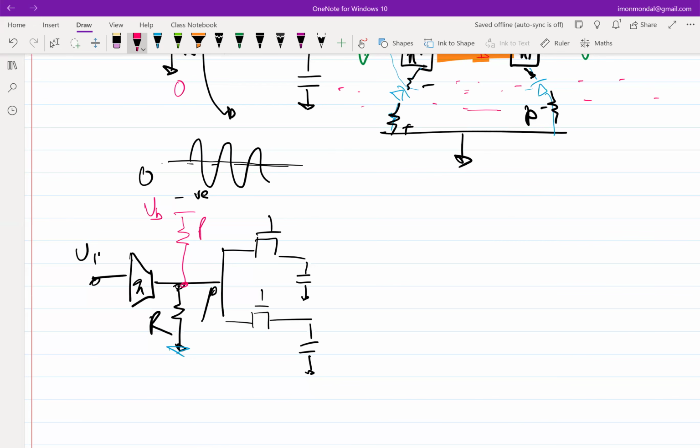But obviously, if you have this RB, if you want this voltage to be of a certain value, which is equal to VB, what should be the relationship between RB and R? Let's say I apply VB, I want approximately VB here. So what should be the relationship between RB and R? RB should be equal to R, much greater than R, less than R? Much less than R, right? But if you have much less than R, then do you foresee a problem? Bias will be set, but signal-wise, the effective resistance reduces. So can you suggest a fix?